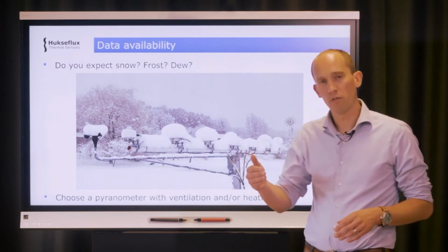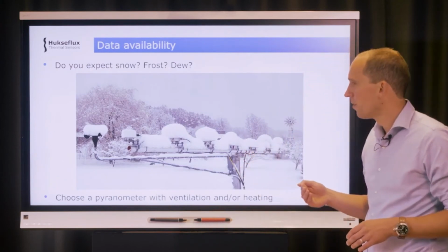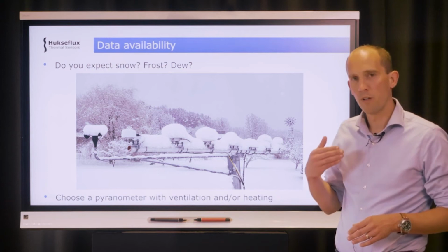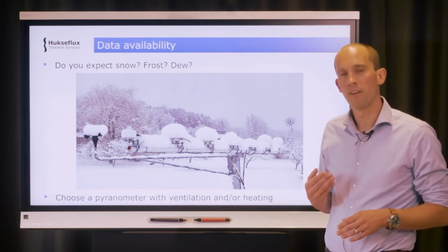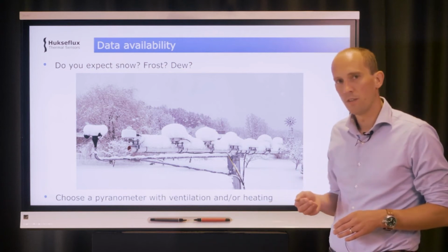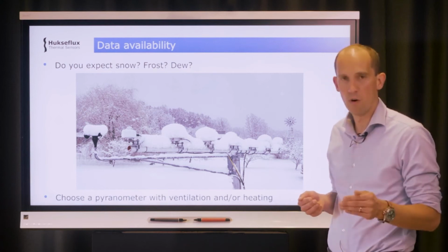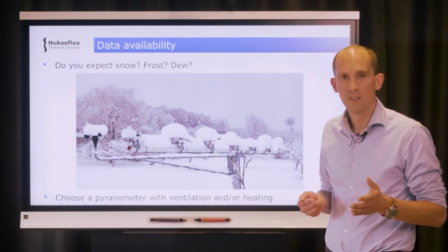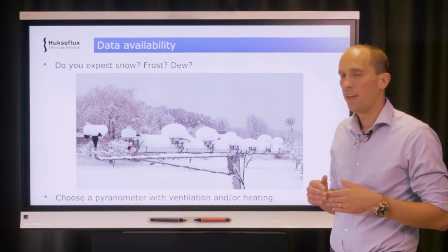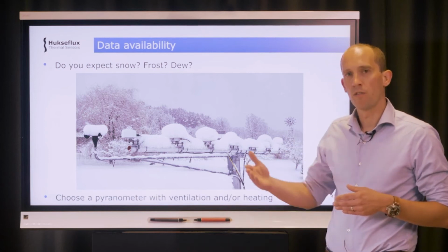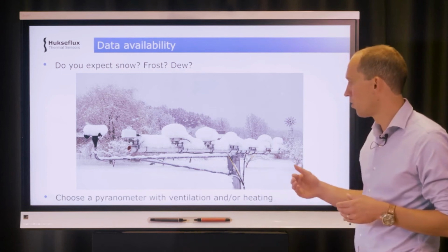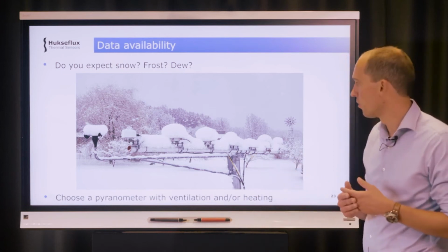Now when choosing an instrument, one concept that we talk about a lot is the concept of data availability. So if you're going to measure somewhere, ask yourself, do you expect snow, frost or dew? And in cases where these events occur, you want to choose a pyranometer with ventilation or heating.